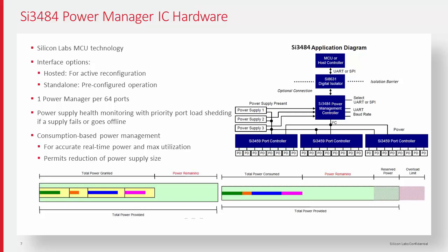Yeah, a little bit about the system coverage. The general way that these products are presented in the market is kind of this call and response interface between a host SoC and this PSE IC. This call and response interface generally requires the host performing an action and then waiting for an interrupt and then responding to that interrupt, etc. So you can kind of get this action interrupt response system. One benefit that the Power Manager offers is that we take all of the control code for that out of the customer's need to worry about.